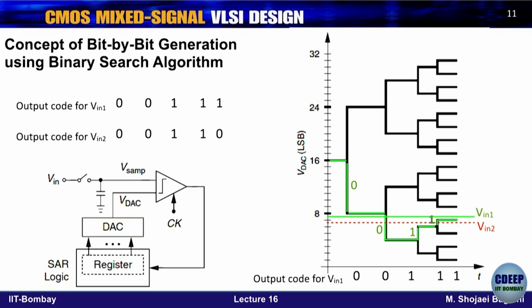Okay. Now one thing which is very important is that this comparator should have the resolution required by this ADC. That is one. Second, the DAC also should be better than this ADC, so that the reference levels which are produced are themselves better than the LSB error of the target ADC.